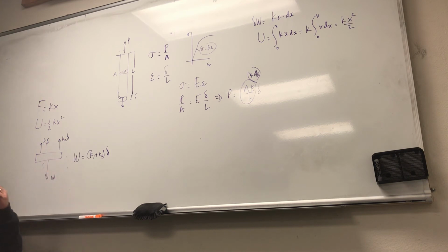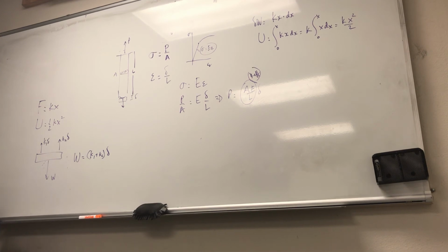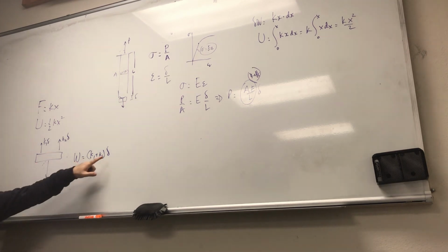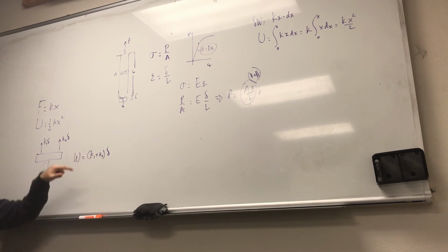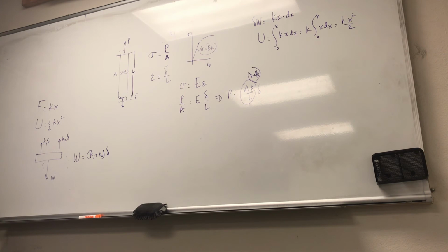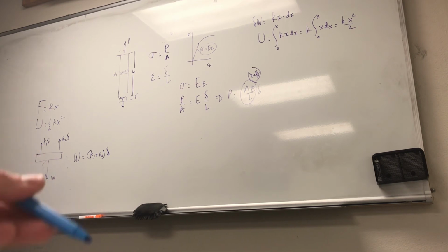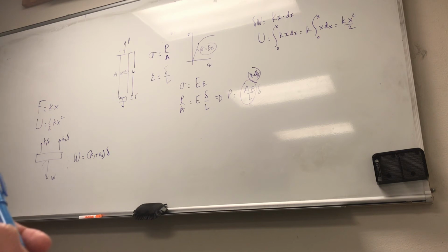And remember, for springs, you have to always think of Hooke's law. Force is equal to something times displacement. This is the force, this is displacement. That means that this group is the equivalent, okay? That's why we have K equals K1 plus K2, and it continues if we had K3, K4, K5, etc. So when you have more than one spring in parallel, if you need to generate more force, what do you need to do? You need to put more springs in parallel, because then you can hold more load, okay? So K equivalent is K1 plus K2.